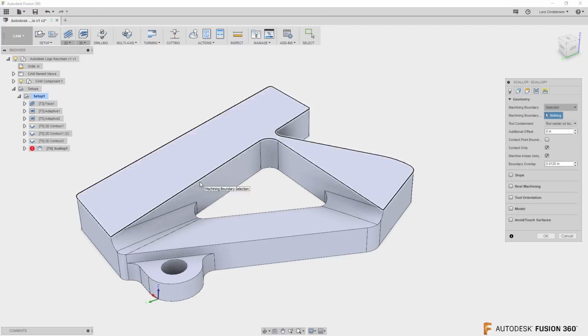If I select in here, you will see that it's almost like Fusion tries to select certain areas. See how the chain is not right here. You probably maybe tried that. But what you can do is select the chain. You see how it's going to machine within this L shape here, pickaxe or whatever this is. Then you can select it again, and now you can move over, and if you select another edge, you will see how Fusion actually reselects or reorders things. So if I select right here, this is actually a pretty good boundary of that toolpath I think I want.